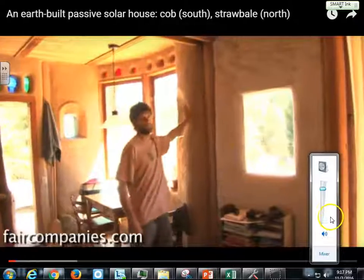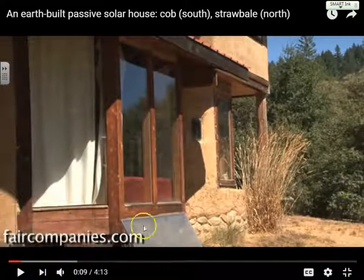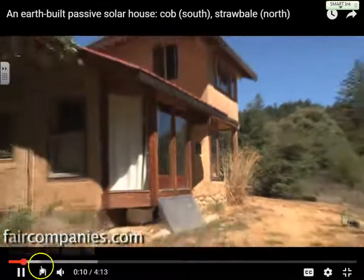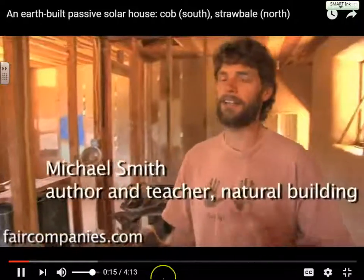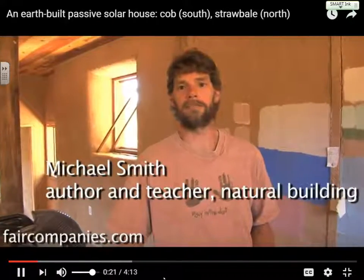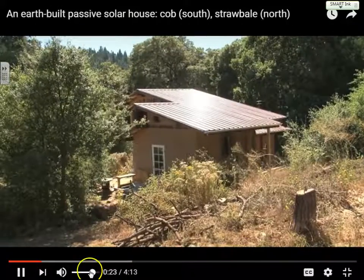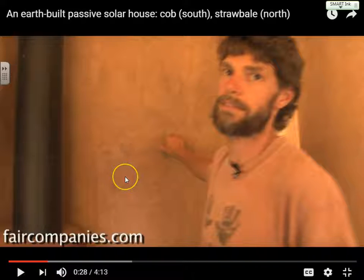This is cob. Cob gives you excellent thermal mass heat storage. So it's a critical part of a successful passive solar design. A building that's going to heat itself and cool itself as much as possible needs thermal mass as well as insulation. Here on the north side of the building, for better insulation, we use straw bale. So this is straw bale, which is exactly what it sounds like. It's bales of straw, and you'll see some details of that in a minute.